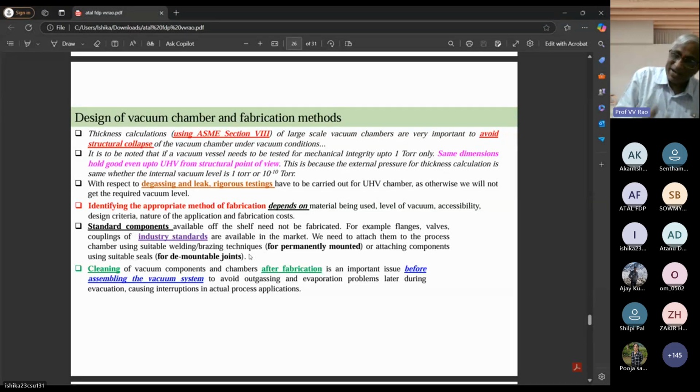That lead can be an ion pump or an electron beam deposition or ion beam depositions. All of them are electrical things. From the outside of the vacuum chamber, you have to pass currents and voltages inside that. How do you do that? Electrodes. But the electrodes are crossing the vacuum chamber. So you have to take all this into account while in the fabrication.